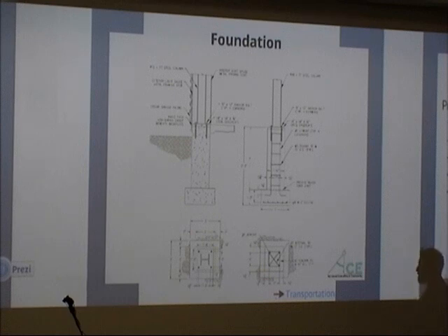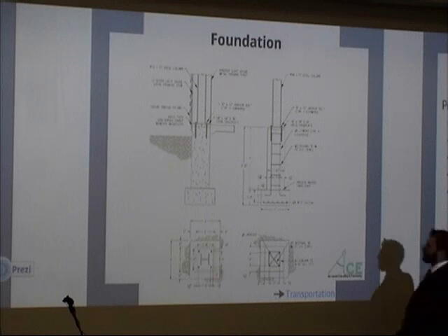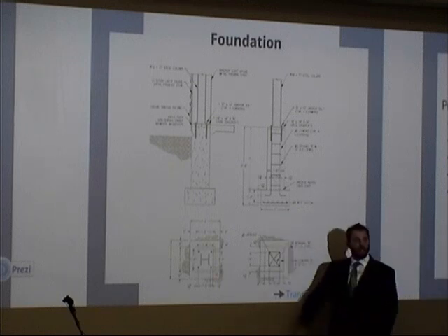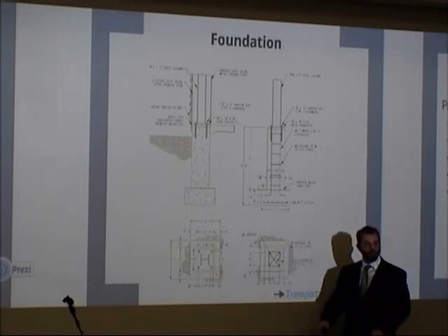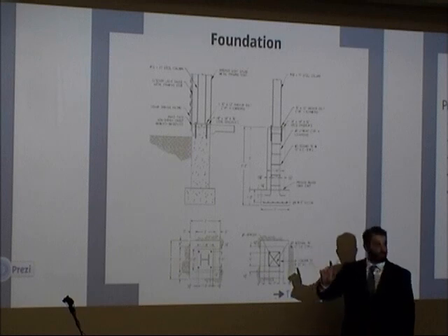Since the load was so low on top of these columns, it practically required no steel. What we did instead was add number 5 rebar at 4 locations to give us some rigidity and extra shear strength. You can see that those are embedded in the footing, so that's the phase construction that I was speaking about before. You pour those in the first half, and they stick out exposed until you're ready to pour the second half.